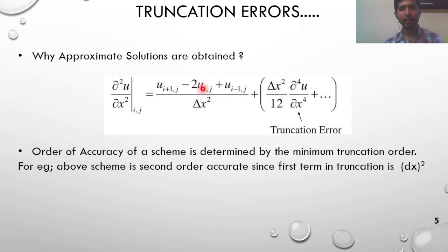The second thing is whether it is a forward difference or a backward difference. Here we have the grid point. Once we generate the mesh, especially the structured mesh, we give some indices 0 1 2 3 4 in the x direction, 0 1 2 3 4 in the y direction. So these are just the indices i and j, in the x direction and in the y direction. Here i plus 1, i minus 1 both are there, for i comma j.